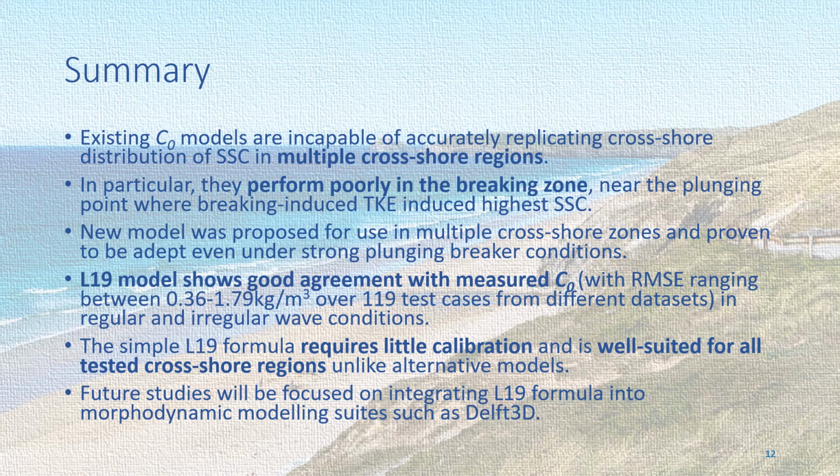In summary, existing C0 models covered in this study were found to be incapable of accurately replicating the cross-shore distribution of suspended sand concentration in multiple cross-shore regions. In particular, they performed poorly in the breaking zone, near the plunging point where breaking-induced turbulent kinetic energy induced highest concentration.